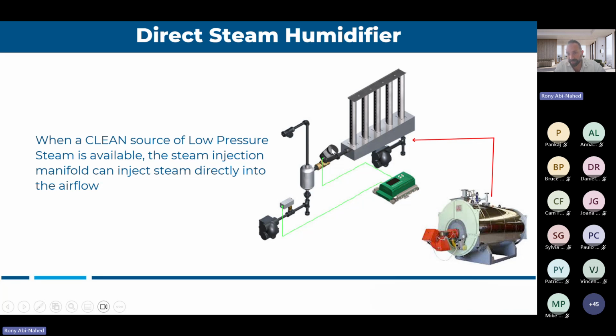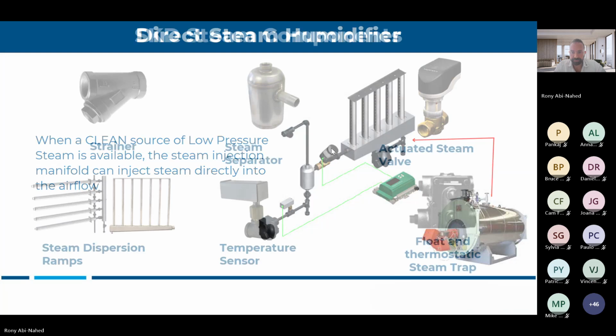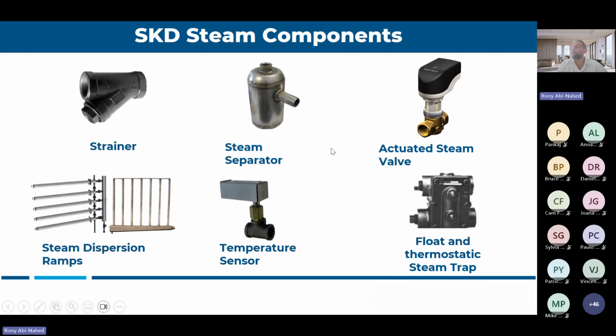Then you connect directly to your grid and push your steam directly there. Again, maximum pressure on this application is 15 psi, so you can go from 5 psi to 15 psi. You can't go higher than that. So make sure also to have a pressure relief valve to get your pressure down to 15 psi. That's mostly the equipment you need when you go with direct steam.